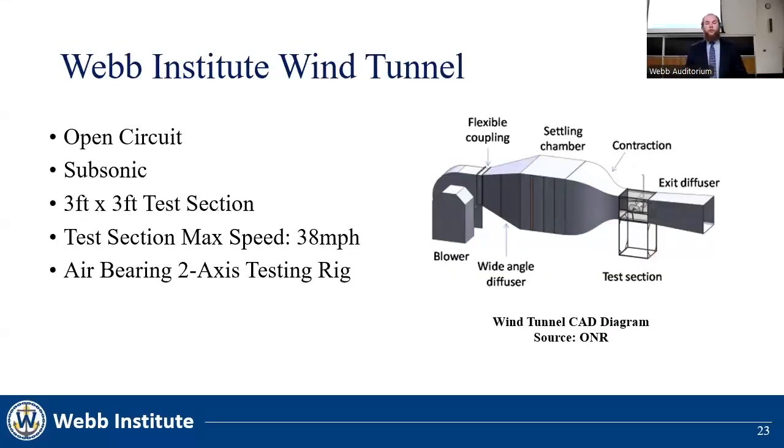The Webb Institute wind tunnel is an open circuit subsonic tunnel. The figure above shows a CAD diagram of our wind tunnel. The Webb tunnel has a maximum test section speed of 38 miles an hour and is equipped with a 2-axis air-bearing rig.